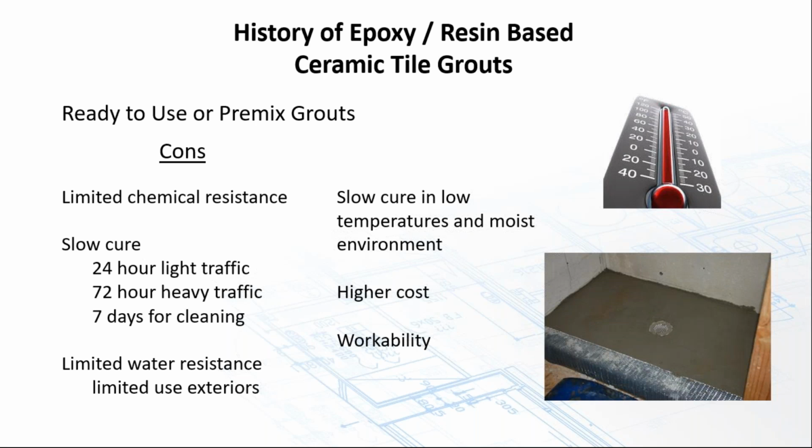Slower cure times with them: 24 hours for light traffic, 7 days for cleaning. And like I mentioned earlier, limited water resistance and limited use on exteriors. Don't use this in a pool, a fountain, a gang shower, or in areas subject to continuous water. Residential use in the bathroom, showers, absolutely, no problem at all.